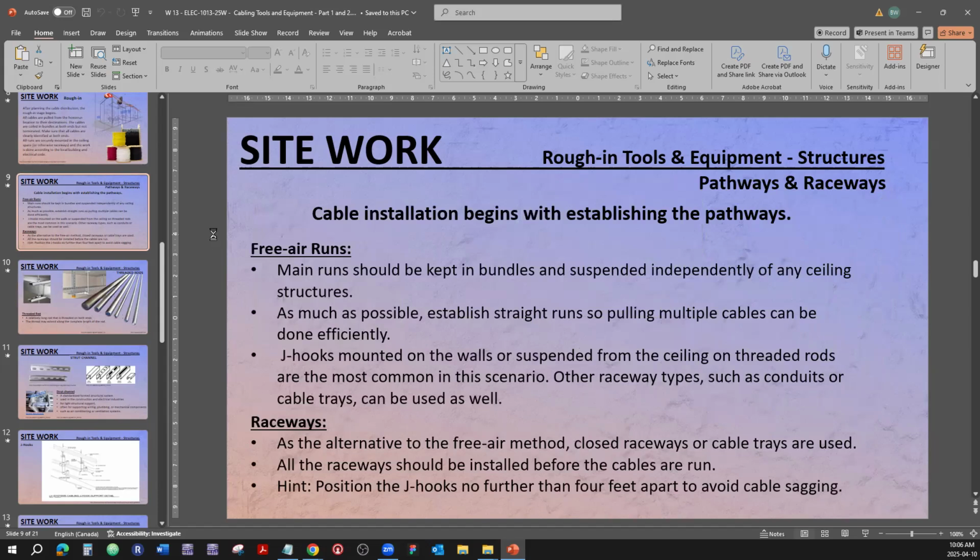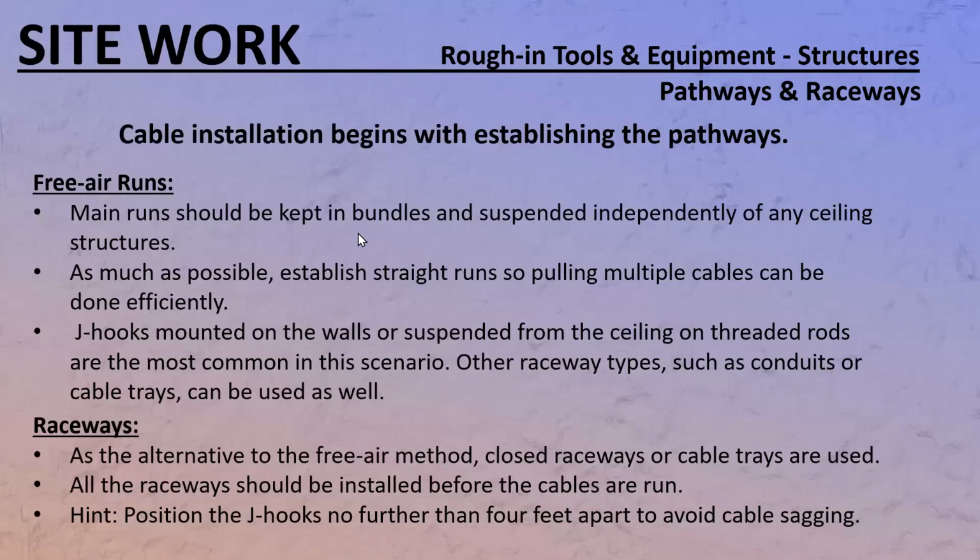All right, that's where we're going to start. Pick up on this thing here. Site work cable installations begins with establishing the pathways. Now, what do I mean by establishing the pathways? What you do is try to establish as many straight runs as possible.